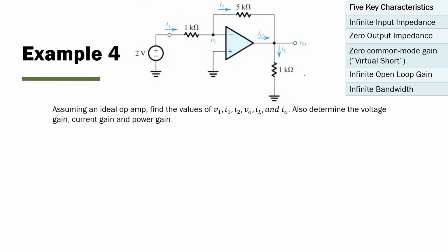And we know that V is equal to IR. But if the resistance here is infinite, that means I is equal to V divided by infinity. So that means there's zero current coming into here, and zero current coming into this positive terminal.